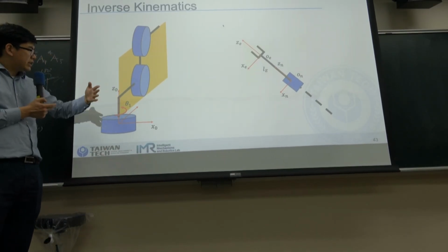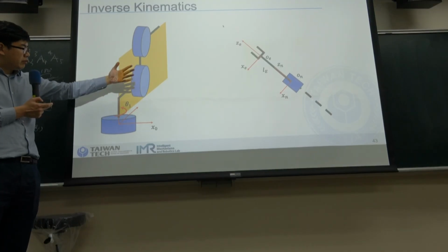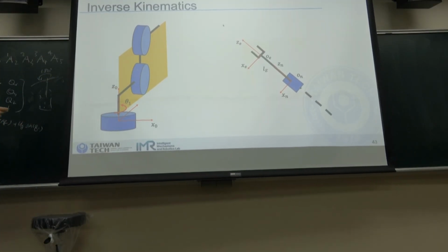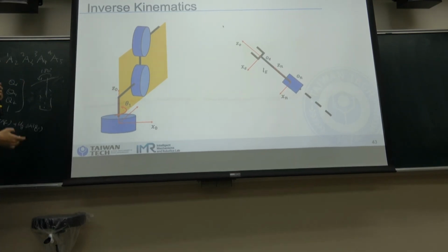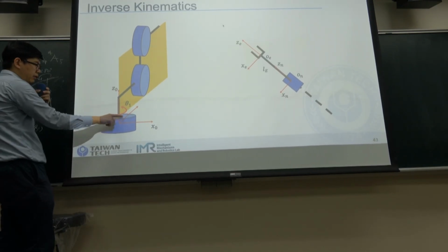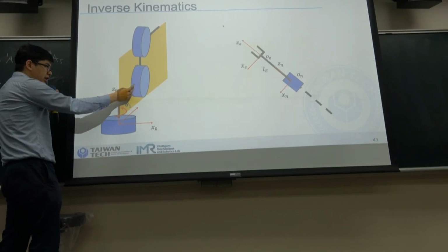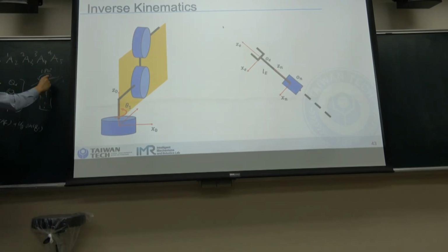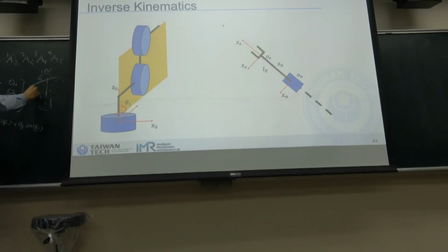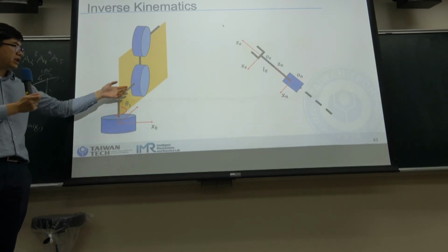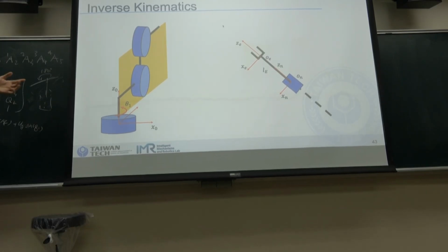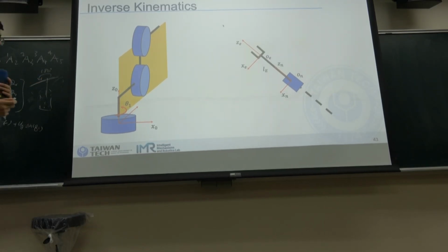So theta 1 must rotate so that the robot rotates into this plane. And within this plane, we'll have 2 solutions. One will be something like this one, aiming in front. If you rotate 180 degrees back to this point, it's also within the plane. So for theta 1, we'll have 2 solutions. And the difference between these solutions is 180 degrees.